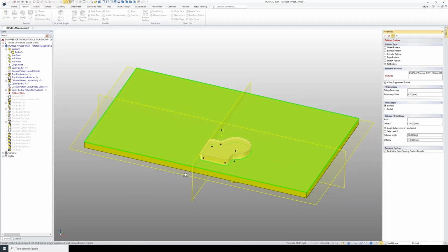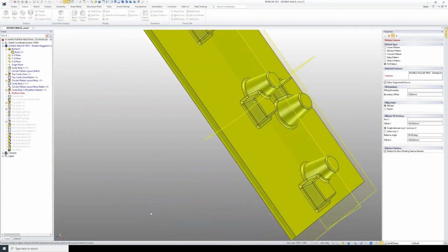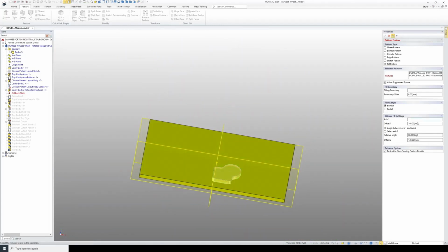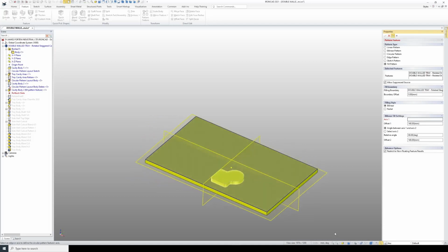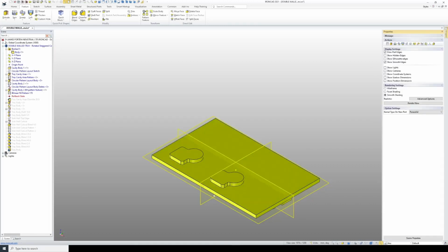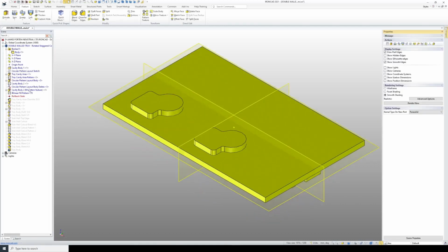And now I can add that other body to it. I can select the filling boundary, which is that face. Again, we're doing the underside, and for the axis I just want it the same as previously, which is this edge here. And again, I've got a preview, and I'm just going to leave these values for now, because we're going to link this pattern with our sketch pattern.